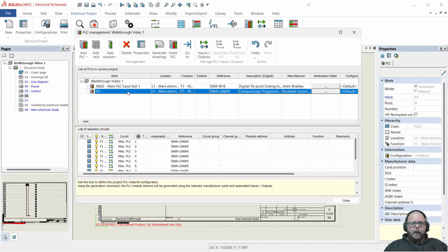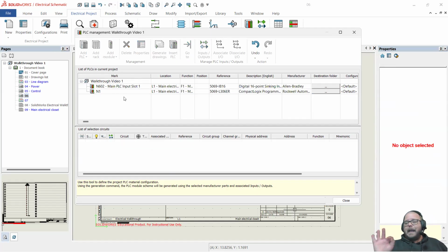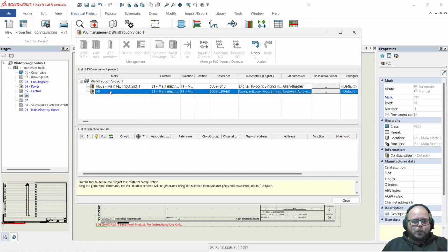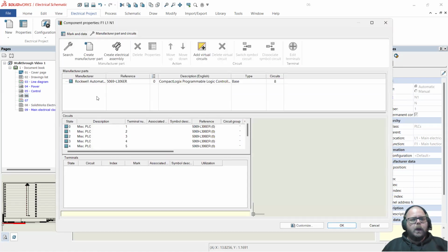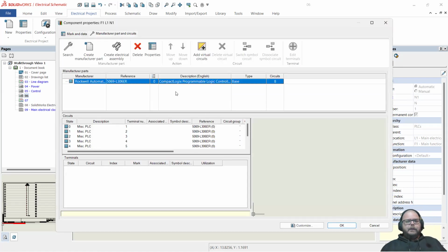But right now, the top level is fine. There is one caveat, and I want to warn anybody watching this that might be in Allen Bradley land. The 5069, let's go and I want a property and I want to look here. Any of those 5069 processors do not come with power terminals. Ask me how I know this.